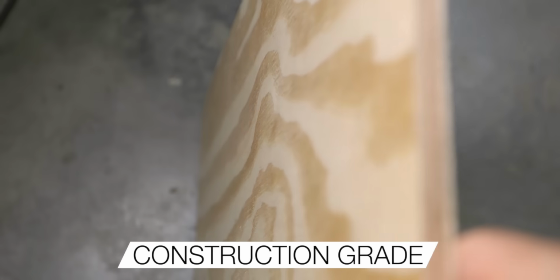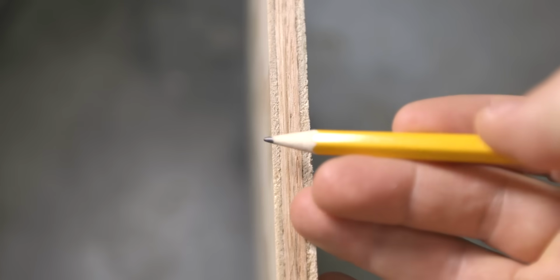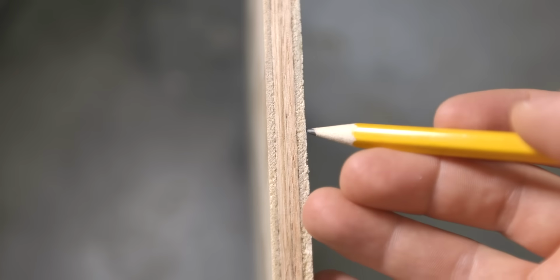So for example, the fewer the plies, the weaker the plywood, or the less stable it is. The more plies it has, the more stable it is, the stronger it is. For example, this half-inch construction grade plywood has 4 plies, sold in 4x8 sheets, and has a pretty rough surface even after it's been sanded.